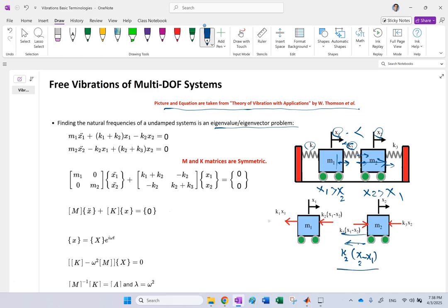Now look at this one and look at this one. Look at these two forces. Are they the same or not? They are. You see, the only difference between them is a negative sign, but also the directions are opposite. Well, if you reverse the direction or you put a negative, that has the same effect. So you can see that these two forces in different directions with the negative sign is like two negatives applied, and these are the same force. So it doesn't matter really whether you use X1 bigger than X2 or X2 bigger than X1. Just pick one and move on and get your forces, okay? The result is not going to change.